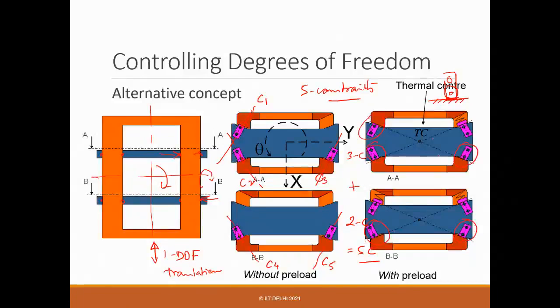So the other 3 you connect through springs, right? Which provides you the preloading. So you can make it adjustable also, so that you can change, right? These are the constraint direction, but by adjusting them you can preload, right? And then you can get the benefit and you can ensure that the contacts are made all the time.